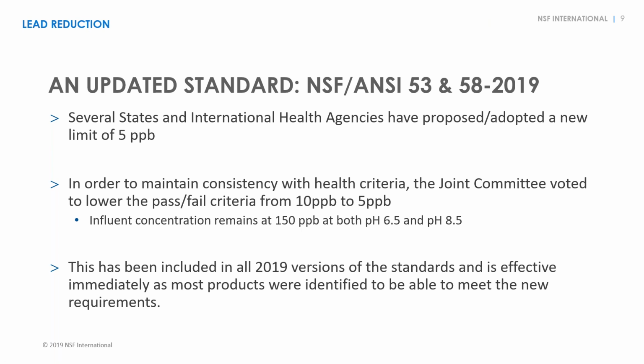53 covers products that typically contain activated media, filtration types of products, whereas 58 is the standard associated with reverse osmosis. So what occurred was that there had been proposed changes and adopted changes now of a drinking water lead criteria of 5 parts per billion. The previous version of the NSF ANSI standards had a pass-fail criteria for products to meet a reduction of lead in the drinking water at 10 parts per billion.